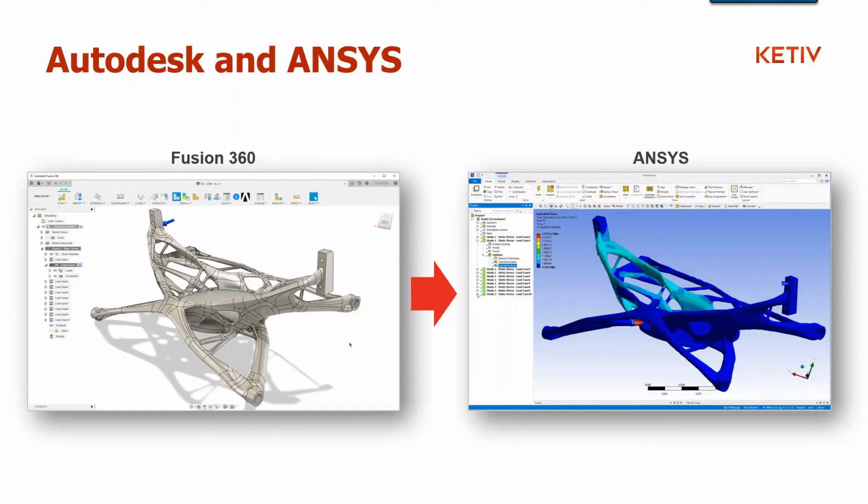But if you have Ansys Mechanical installed on your desktop and Fusion 360, as soon as you run a generative design part, you are going to get this little icon that you see here. And you're going to be able to export out to Ansys Mechanical. So you're going to get all your load conditions, your materials are going to populate as well. And you can use Ansys Mechanical to further validate some of those results.